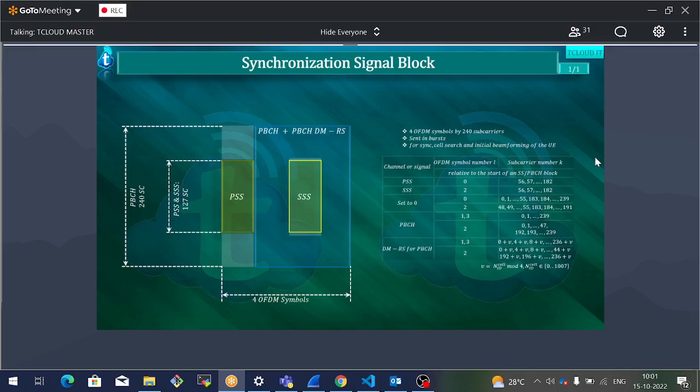If different channels are placed at different positions, the mobile equipment cannot detect which symbols are carrying what channel data, because all the symbols look the same. They are all QPSK symbols or 16 QAM symbols or BPSK symbols, whatever. Everything is a symbol. Everything is carrying digital data, but you cannot detect what the digital data is carrying.